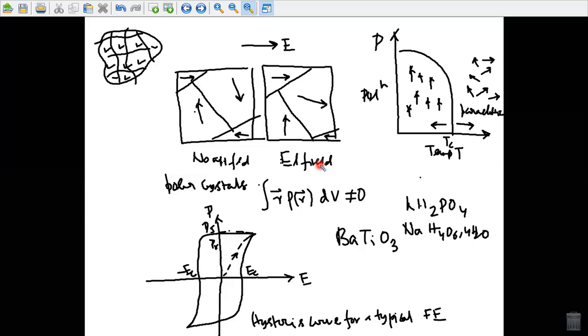So ferroelectric crystals often have unusual properties. Rochelle salt, that is NaKC4H4O6·4H2O, which was the first ferroelectric crystal discovered, has both an upper and lower transition temperature. The crystal is only polarized between the two transition temperatures. The TGS type of ferroelectric, including triglycine sulfate and triglycine selenate, is another common class of ferroelectrics and has found application in IR detectors due to its pyroelectric properties.